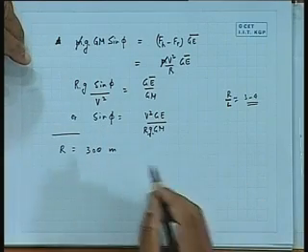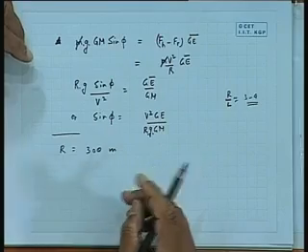Okay. The radius of turning relative to the length of the ship: normally for a large ship it lies between 3 to 4, or around 4, you can say. But for navy ships, with very tight turning, a double rudder ship can be as small as even 2. It can turn. Radius is 2, that means diameter is 4. Remember that.